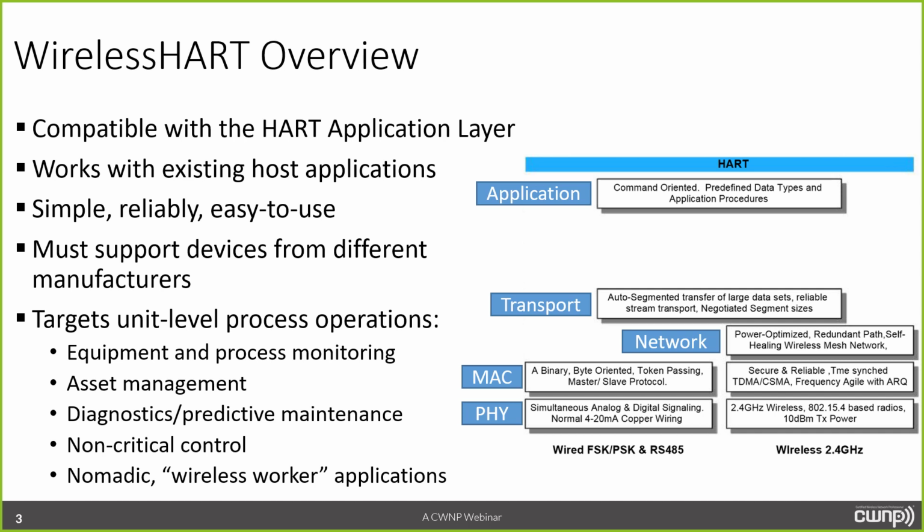HART is a very simple protocol. HART is very reliable for some unique reasons that we'll get into. One of the key things about HART, the wireline protocol, when doing FSK, PSK, RS485, as you see in the graphic here, is that it is a continuous current protocol.